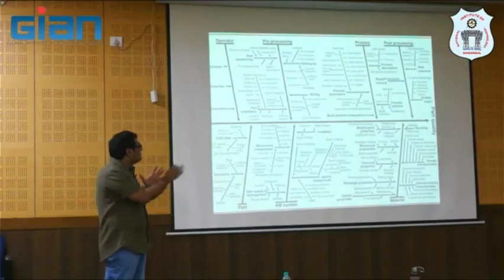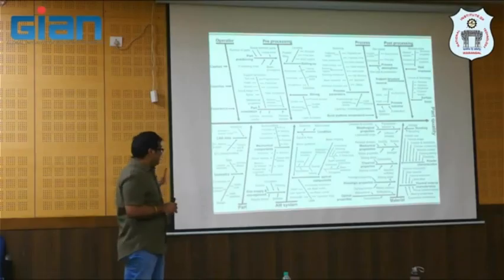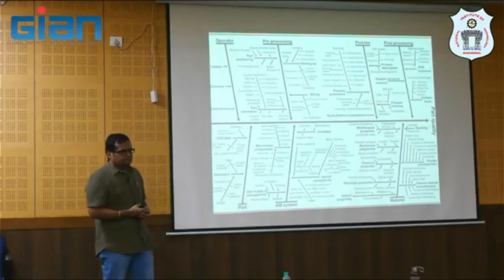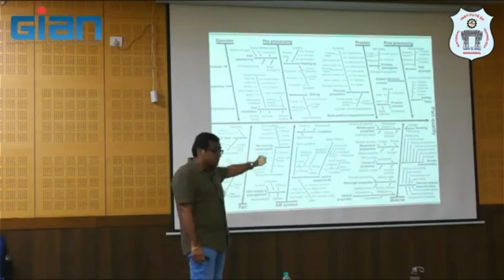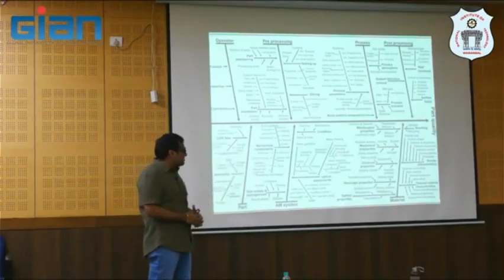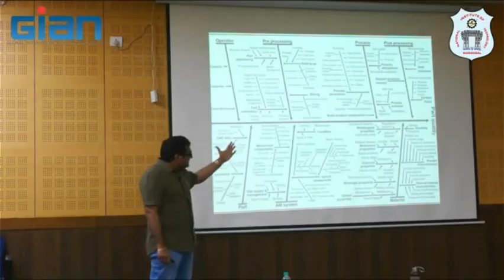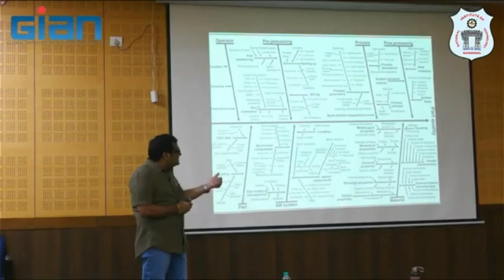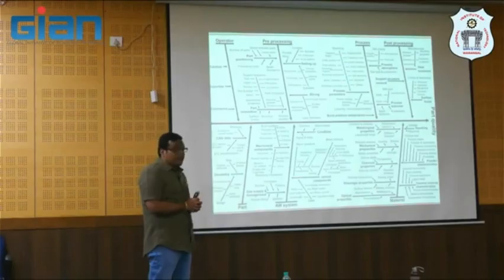And if you look at the part quality of any typical powder bed system, at least 200, 300 parameters are going to affect it. Even from the previous lecture, we came to know that there will be a huge effect from the feedstock powder: the chemical properties or powder characteristics, metallurgical properties, rheological properties of your feedstock material, and then optical properties.